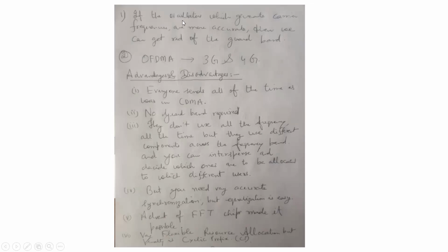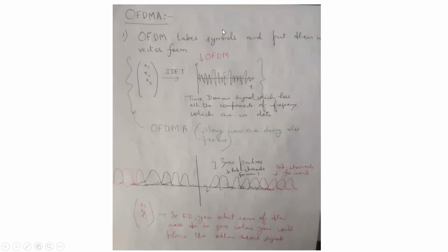Now, what is the point? The point is that it is very difficult because there is no guard band here. So even the pulses are overlapping with each other. So why is it possible? This has been made possible because of the high quality algorithms used for carrier synchronization. You require carrier frequencies to superimpose your data onto these carrier frequencies.